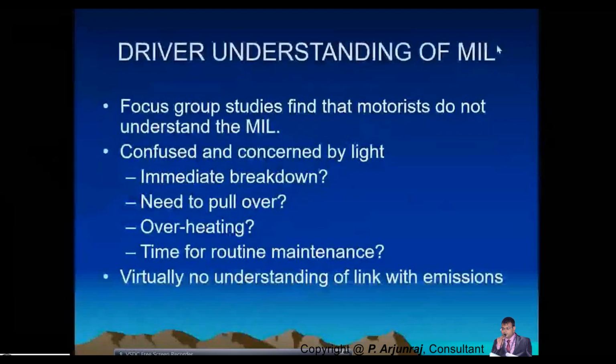Okay, this is very much important. The knowledge of this MIL is very much important because you should know the purpose of the MIL, and what actions you need to take accordingly. You should not fear an immediate breakdown just because of a light indication, thinking the issue is very heavy. You should understand what the indication is all about and take the correct action.